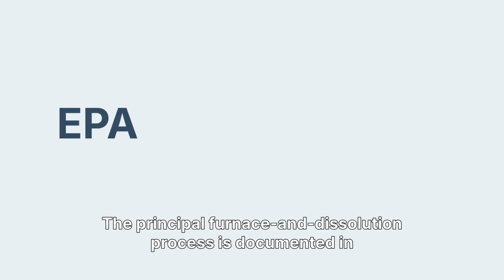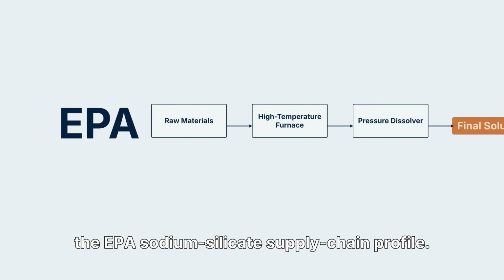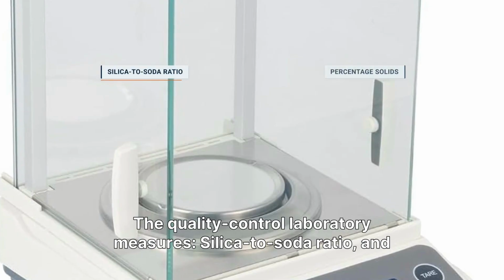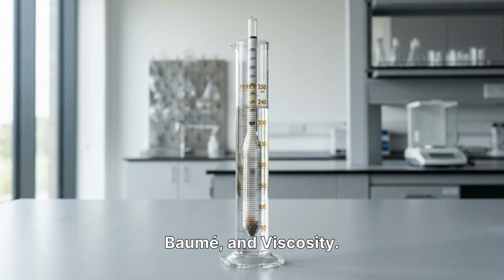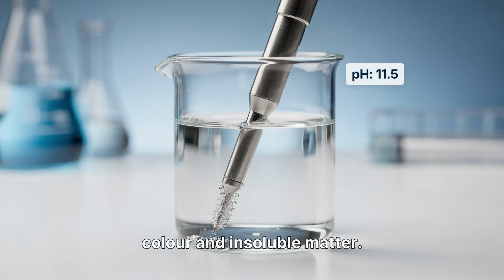The principal furnace and dissolution process is documented in the EPA sodium silicate supply chain profile. Manufacturing sodium silicate is not simply about melting sand. The product must be engineered for a specific application. The quality control laboratory measures silica-to-soda ratio and percentage solids. They also test specific gravity or degrees Baume and viscosity. Finally, they test pH and alkalinity, clarity, color, and insoluble matter.